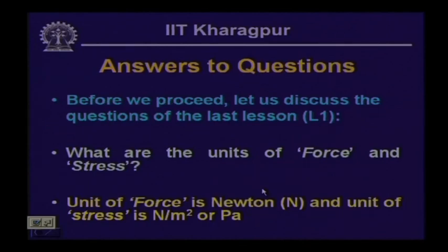Before we go into the details of the analysis, let us look into the questions which we had posed last time. The first question was, what are the units of force and stress? Well, these are given within the lesson itself, and I am sure all of you have got it. The unit of force is Newton and the unit of stress is Newton per meter square or Pascal. This can also be represented in terms of megapascal or gigapascal.